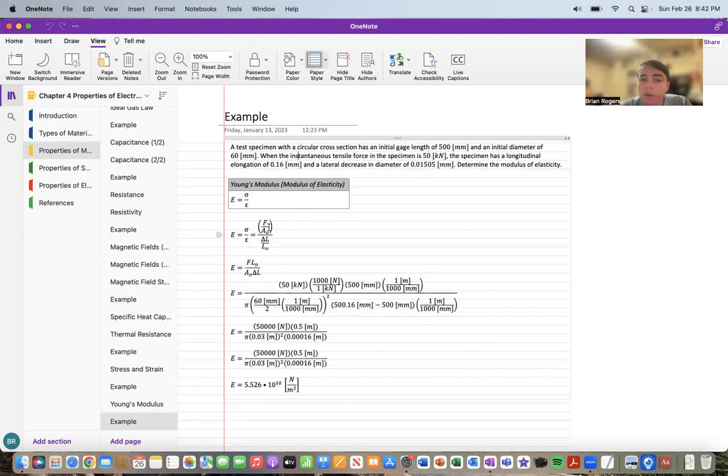So here, remember, Young's modulus is our stress over strain. Calculating the modulus of elasticity: stress over strain is force over area, divided by change in length all over initial length. So just rewriting the equation, since it's a fraction, this denominator will move to the numerator, and the denominator of the fraction in the numerator will move to the actual denominator.